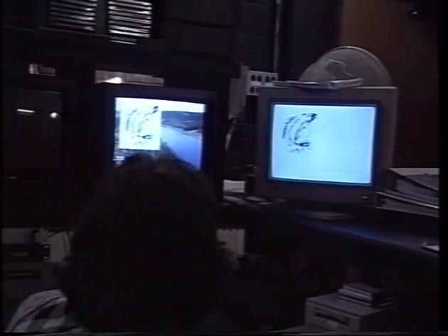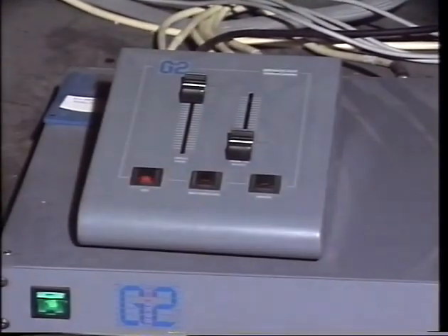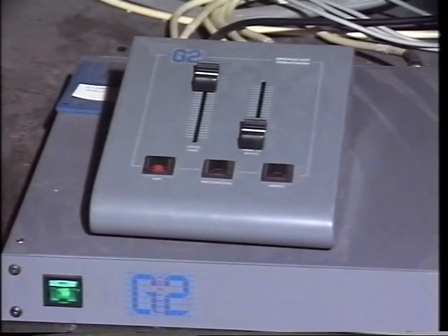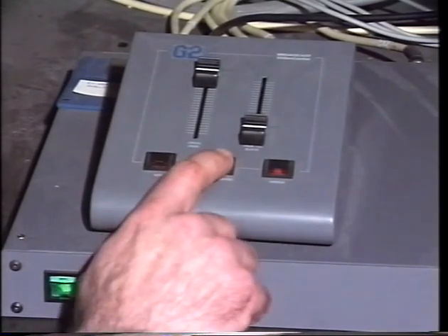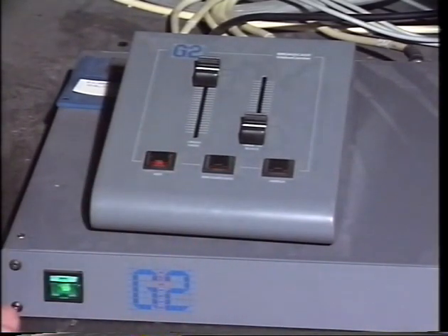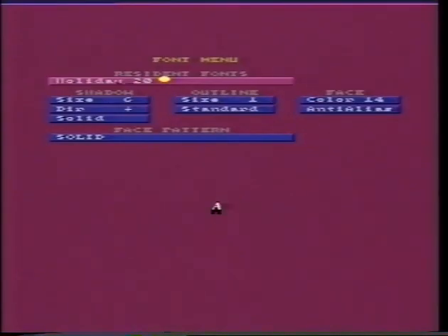The images from the Amiga are combined with video via a Genlock and keyer. Here the G2 systems model is used, a full component unit. The G2 mixer produces crossfades between the Amiga and video channels, or the full signal may be taken from the Amiga for dumping graphics and animations to tape. The background video channel removes the Amiga from the system. The key allows the Amiga to be keyed over live or still video. The ability to key Amiga pictures over video is particularly useful for titling.